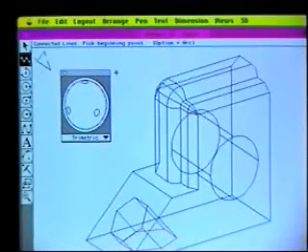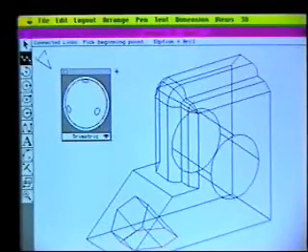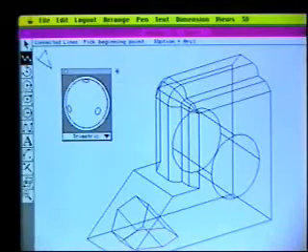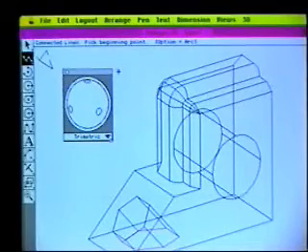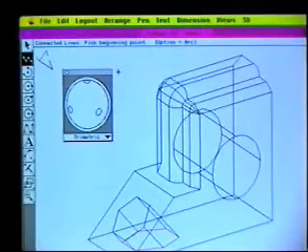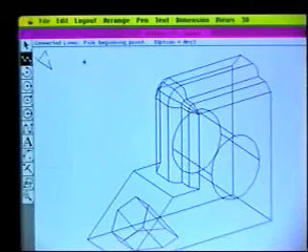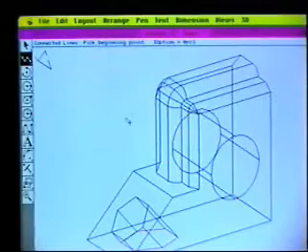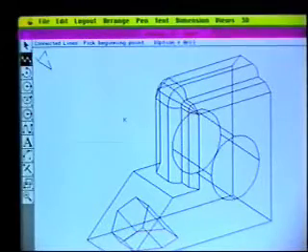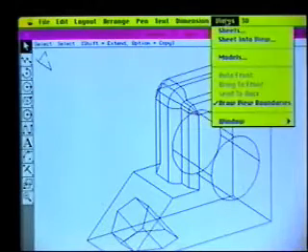This is actually only half the story, though, because certainly we want the ability, and we provide you the ability to design in 3D, but the purpose of vellum is to get you to a 2D production drawing of your 3D design. That's what it's all about, so that's what we want to do next. I'm going to close my trackball. And the nice thing about vellum is that it only takes a single command to get a 4-view drawing of this part automatically. So all I will do is go to the Views menu, and here's a command